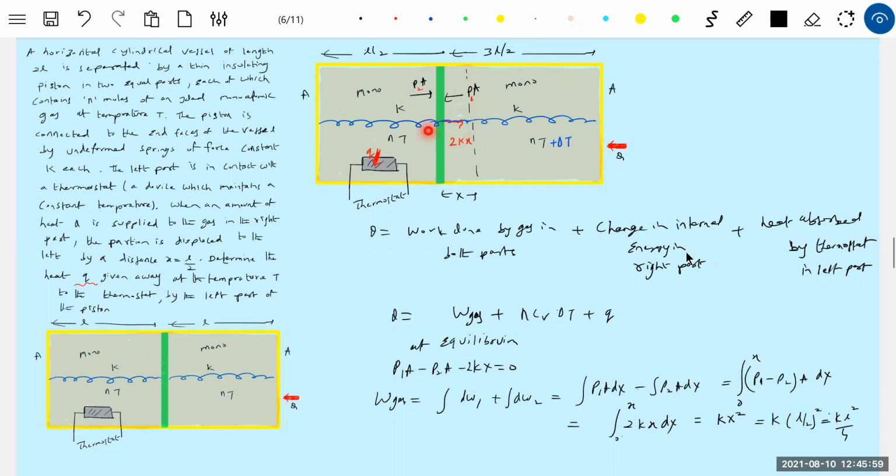If you remove the springs, then see, sir, what will happen? Okay, sir, springs are there. Okay, you remove the spring. Then nobody is there to accept it, means work done by gas is zero. It will become like a free expansion. So always say mechanical work done by the gas. There should be an agent who should be in a position to accept it. Who is that agent now? The extra agent is the spring. The spring is going to accept that energy.